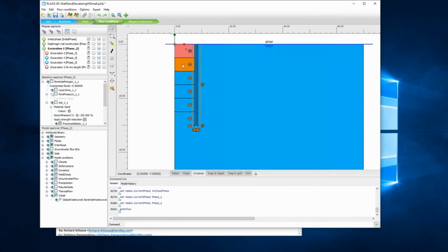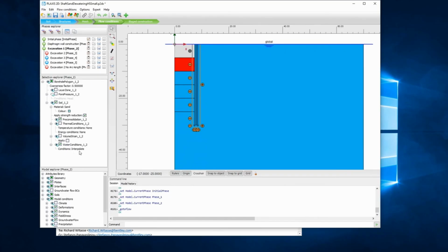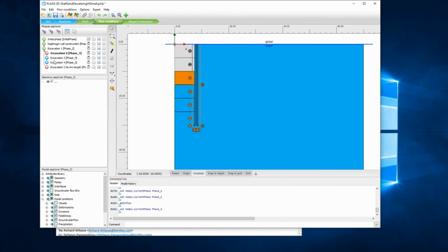This one is dry, and I forgot to mention, this one in between will simply consist of an interpolation, using the option interpolate, a vertical interpolation between the pore water pressure in the top cluster and the water pressure in the underlying cluster. So it would just draw a straight line between 0 and whatever value is defined here by the global water pressure. And this is the same I will consistently use over each phase, over and over again. Okay, and this is how I will define my calculation.